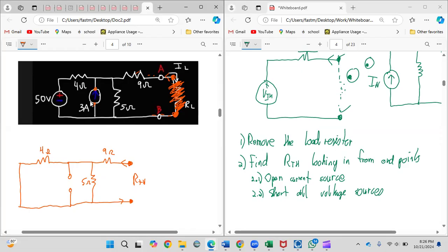So what you could do actually is take off the voltage in the circuit, get a multimeter, plug out a resistor, and plug your terminals across those two points. It will give you the equivalent resistance looking in at that particular point.